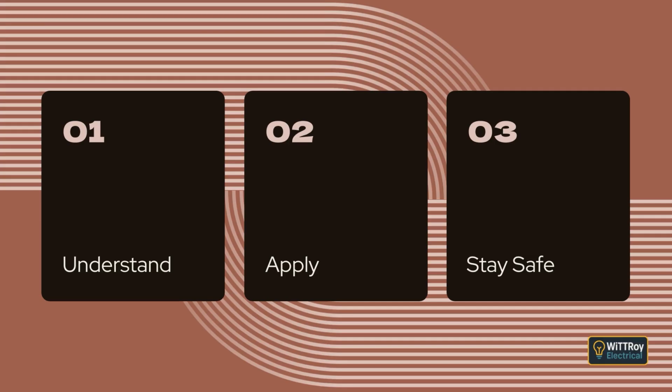If a multi-core cable includes a protective earth within a screened layer, the individual conductor does not need green and yellow insulation. The core may instead be marked at its ends where it joins the earthing system. Some insulated protective earths are made using materials that cannot be colored green and yellow. In these cases, sleeving at terminations is recommended unless the conductor's purpose is already clear.